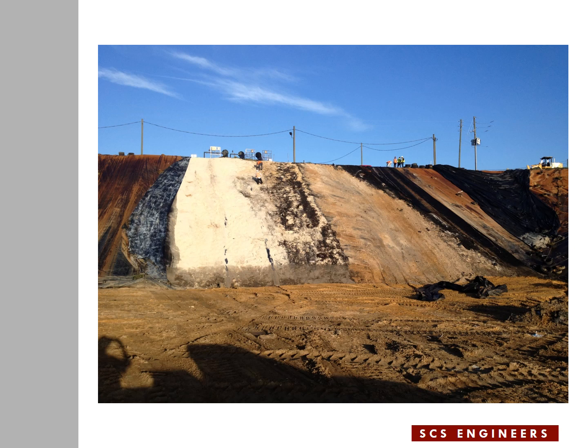This area is bounded by 2 lines extending from the top to the bottom. The right side line has a black area to the right side of it. That is the existing geomembrane in the lining system that didn't get damaged. So there is a boundary line of fire damage in that area. To the left side of the tan area is a line that extends from the top to the bottom. That's also the other side of the repair area. So primarily the tan color area is the repair area for the geosynthetics.